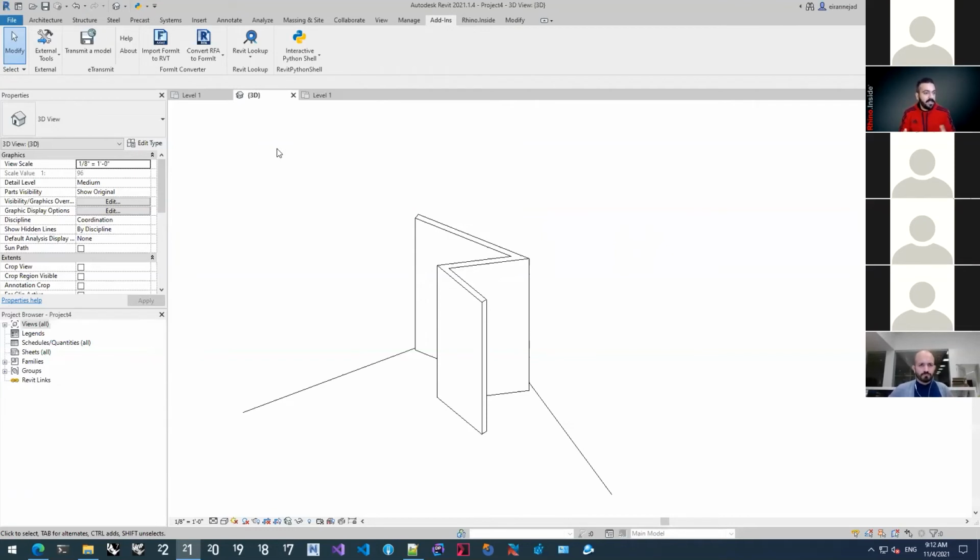In Revit, it's vastly different. We're very used to this, just working with the UI. If you delete a wall, anything that's hosted on that wall is going to go away. If I delete an elevation tag, all the elevation marker types that I have are going to get affected. They're going to lose that reference that they have.